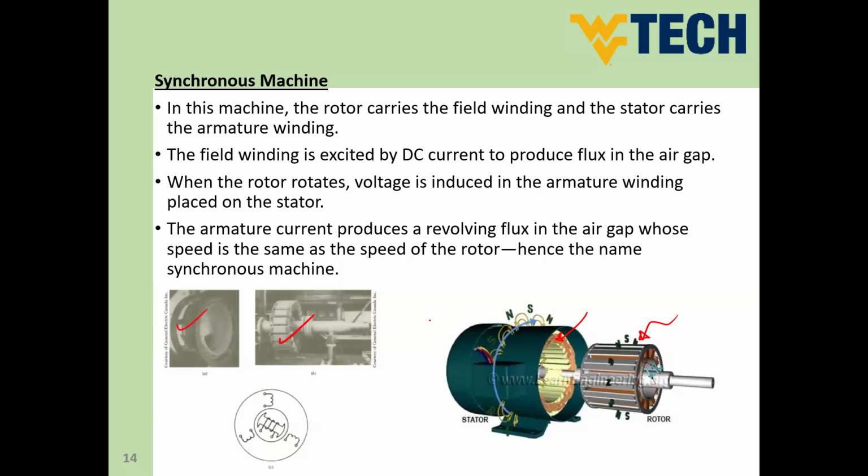This is a relatively big synchronous machine, including the rotor and the stator, in this photo. Okay, so in this type of machine, guys, we actually have two windings. The windings on the rotor side are the field winding, and this will be supplied by a DC source to produce our magnetic field, but the power is going to be very small on these windings.